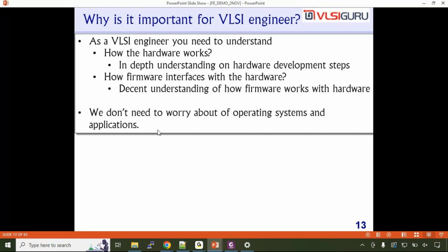So you understood what this firmware is developed by. Is it RTL code or which one? Firmware is developed using embedded C language. Embedded C will finally be converted into assembly instructions through a compiler. Those assembly instructions will be converted to hexadecimal code. That hexadecimal code is nothing but an image, some series of codes that is loaded into the memory. Then my processor gets those instructions and executes them.